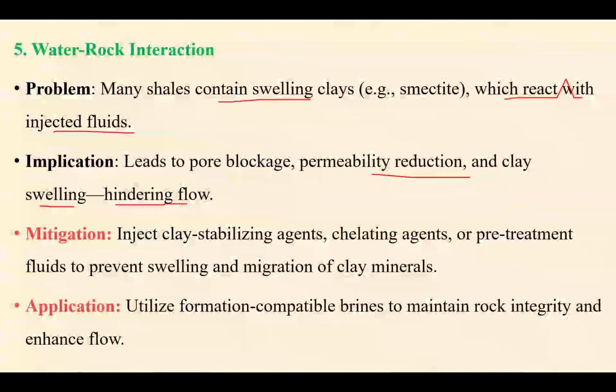And here, how can this problem be tackled? You have to inject some clay stabilizing agent, some chelating agent, some pre-treatment fluids to prevent the swelling and migration of the clay materials. That is very much important.